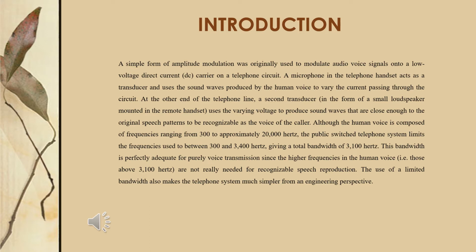This bandwidth is perfectly adequate for purely voice transmission since the higher frequencies in the human voice, which are those above 3400 Hz, are not really needed for recognizable speech reproduction. The use of a limited bandwidth also makes the telephone system much simpler from an engineering perspective.